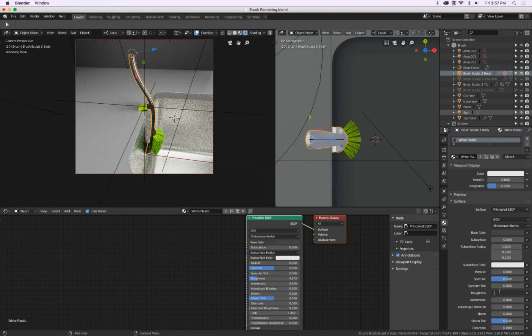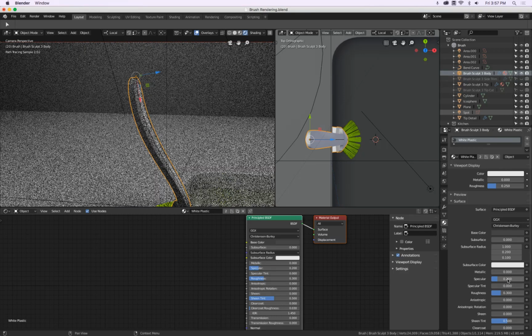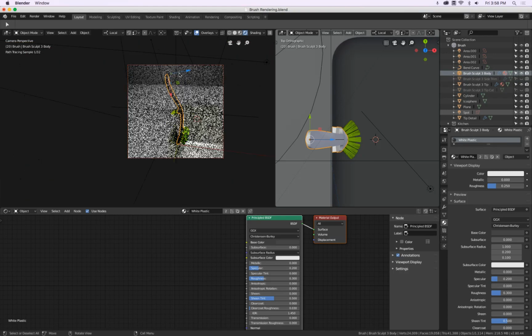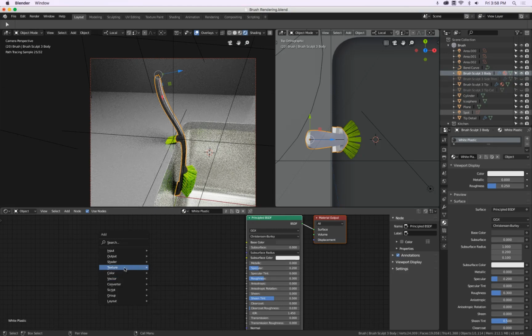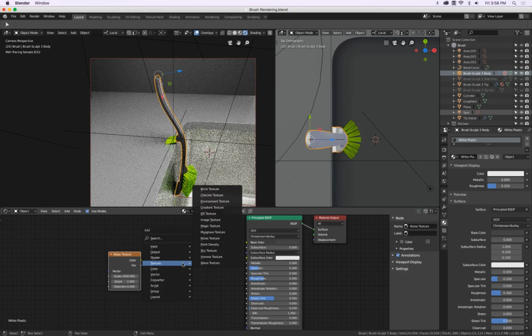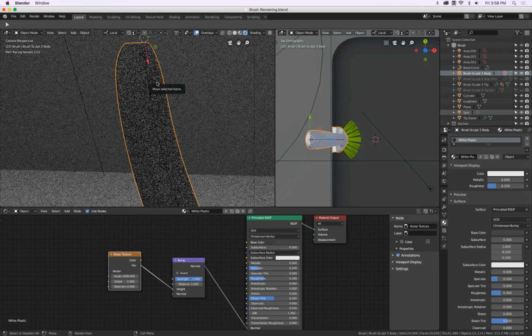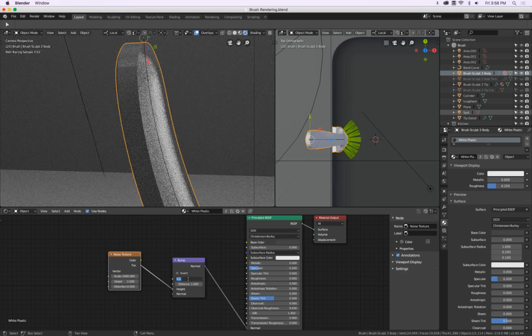And a roughness 0.3, maybe 0.2 for the specularity, so it's not super shiny. Also there we can actually do the same. So texture noise, I know that's maybe 1000. A bump, factor height there to there. Let's zoom in. I want to set this to 0 so I can see the pattern better. Strength 0.1.